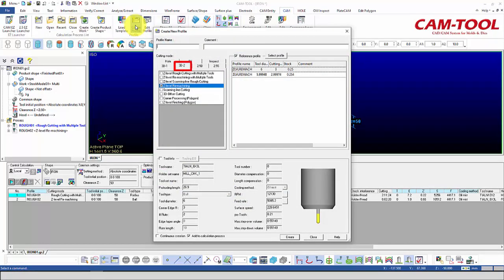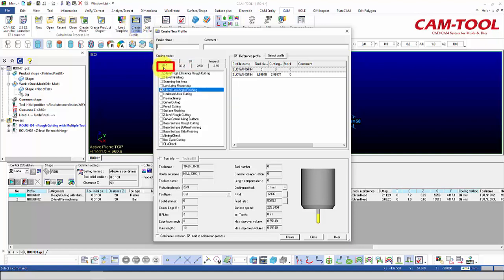The 3D2 tab programs use triangulation mesh, which are designed for roughing and faster calculation times. For semi-finishing and finishing, we are going to use programs from the 3D1 tab. These programs are higher accuracy and are created using surface-based geometry.